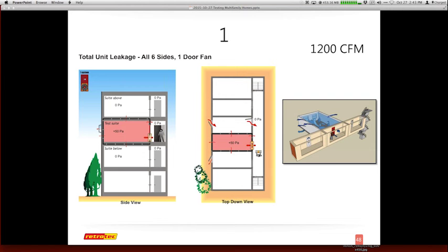He's also asking, these are great questions from Jim Nugent, do I test to the outside or to the enclosed hallway? You always are trying to test to the outside. That's always the pressure that we're trying to compare. So you want to make sure that all of your stairwells, at least one of them for sure, is wide open, propped open, and has a direct path all the way down to the first floor, and that door is propped open. So my goal was to really get outside pressures as I'm doing these types of tests.